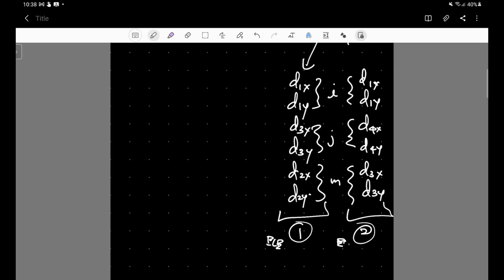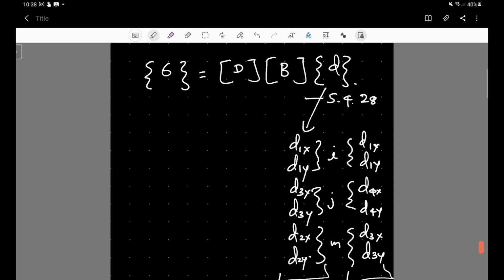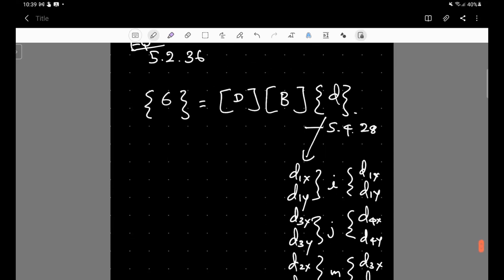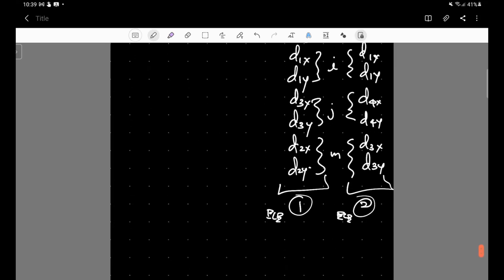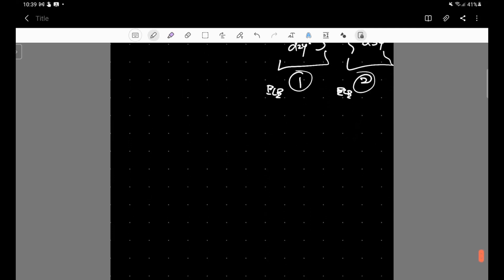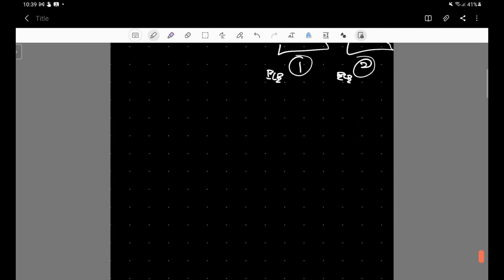This is the only difference, and you can use the corresponding stiffness and B matrices depending on the different nodal coordinate values. So what we obtained for element number 1, if you substitute the equations correctly, is in the supporting material, the reference equation 5.30.